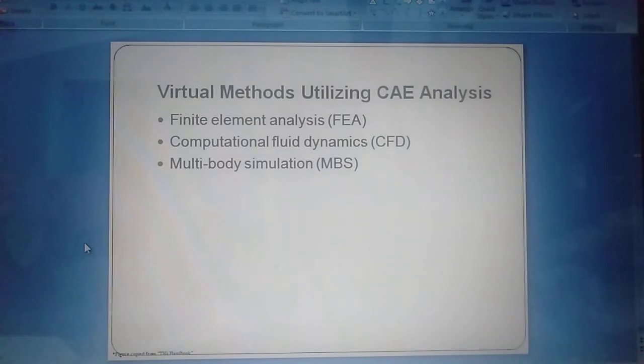They consist of stiff bodies or mass points which are connected with each other or the environment by joints, that is kinematic constraints, and/or by specific force laws, particularly for the low frequency range of motions. The body conditions, for example force, torsional moments, masses, moments of inertia, degrees of freedom of movements, are defined directly in an MBS program.